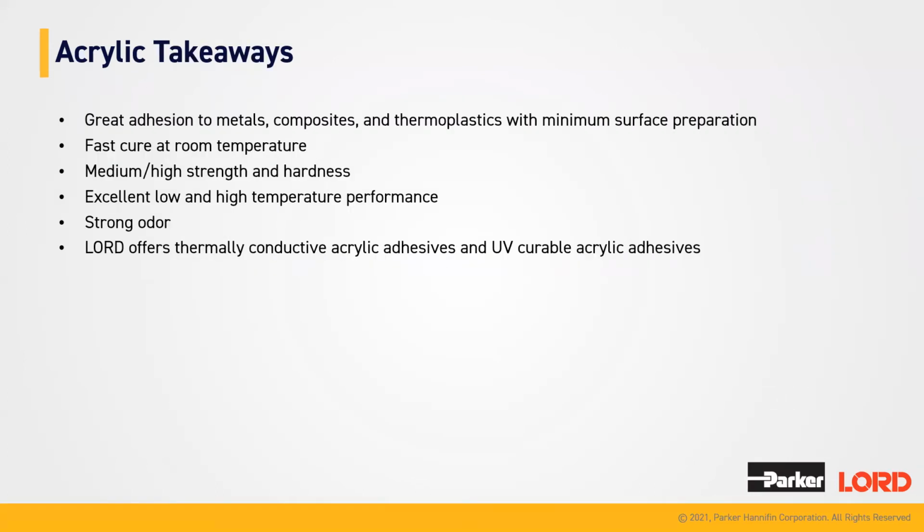Now, acrylic takeaways. Some of the high level things that are the most valuable things that we alluded to. They offer great adhesion to metals, composites, and thermoplastics with minimal surface preparation. They also offer a very fast cure at room temperature, provide medium to high strength as well as medium to high hardness. They are excellent for low and high temperature applications.